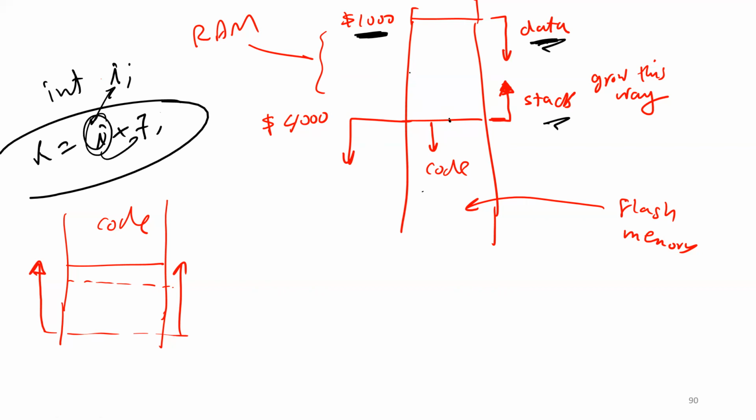For example, I'm going to push 100 bytes. Then I'm going to pull 200 bytes. Does that make sense? No, it doesn't make sense, right? Because once you pull 100 bytes, the stack should be empty, right? The problem is the hardware is not going to give you an error, but this is something you should consider. If you push 100, you have to pull no more than 100, right? But the hardware maybe is not going to give you an error, but it doesn't make sense.